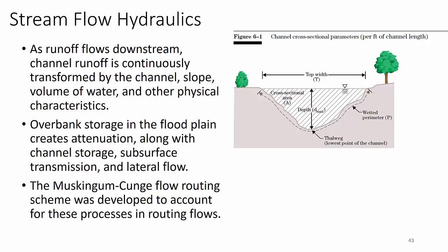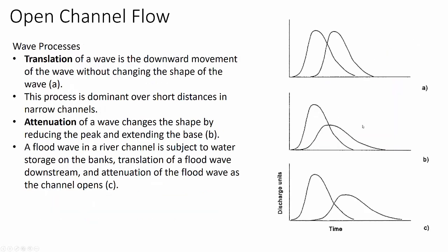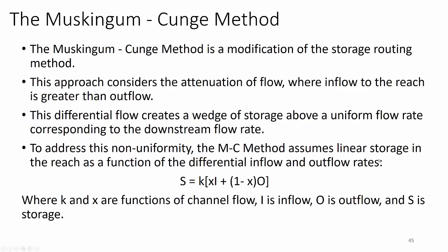We just have to build columns of numbers in order to stage the water in a spreadsheet so that we can not lose it, not destroy it, not create it, make sure we maintain conservation of mass, but move it through in a time-preserved way. So this is really spreading water out over time, because that's ultimately what routing is: spreading water out over the landscape or down the channel over time.